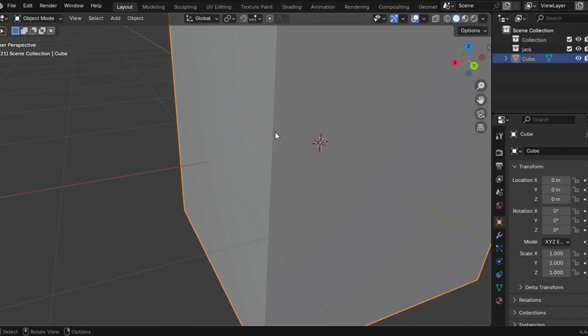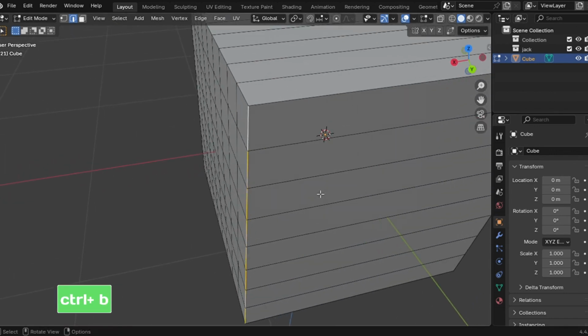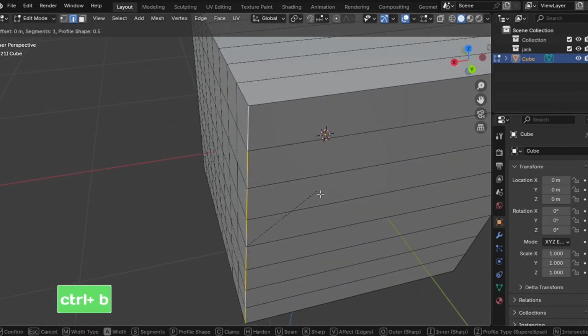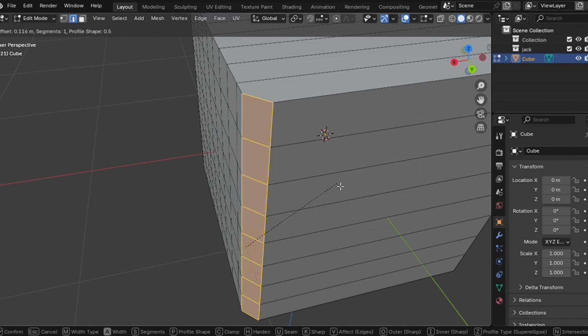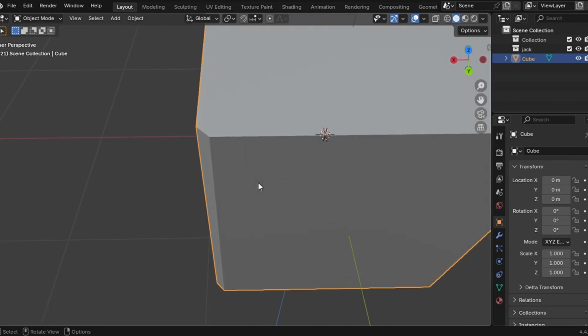So if I want a bevel, I just go to edit mode and select all the edges. Press Alt to select every edge, and holding the Control key, press the B key, which allows you to add a bevel. But what you notice now is that it's not making the edge round or smooth, but opening a 45-degree angle cut. So this is a bevel, but it lacks geometry. That is why you can see it as flat, because this is called a chamfer in Hard Surface. A chamfer is nothing but a one segment bevel.